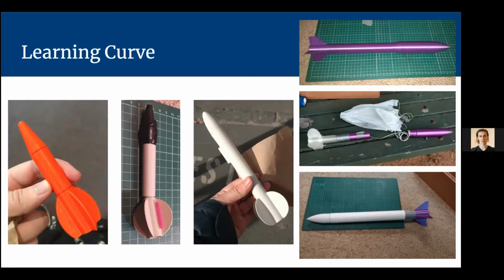The third from the left is a bigger rocket that I fully 3D printed. So yeah, nice big fins. This one was very nice and stable. The one problem that I had with it is I relied on the friction of the motor sliding into the body tube, I relied on that friction to stop the motor from being pushed up inside the rocket.